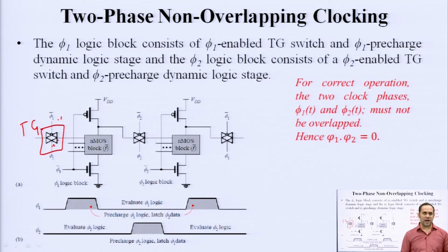And when clock is high, logic 1, NMOS turns on, it passes some signals very easily, and PMOS network is also on because it is working on clock complementary. Okay. So, all type of signals are passed with equal good strength, that is how a transmission gate works as a switch. So, you use TG1 here, say this is transmission gate 1 and this is transmission gate 2. So, this is switch 1 and this is switch 2.